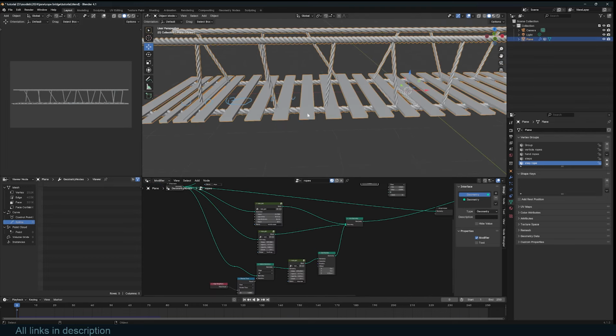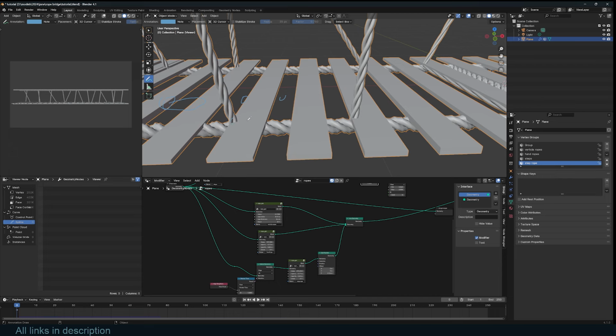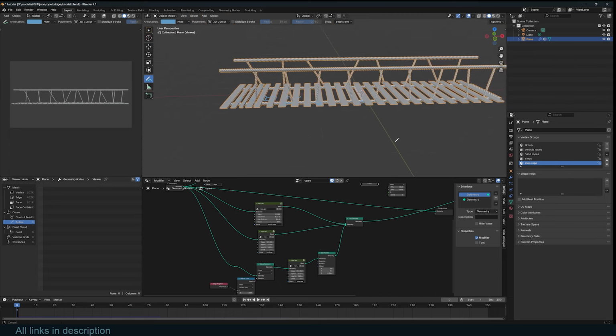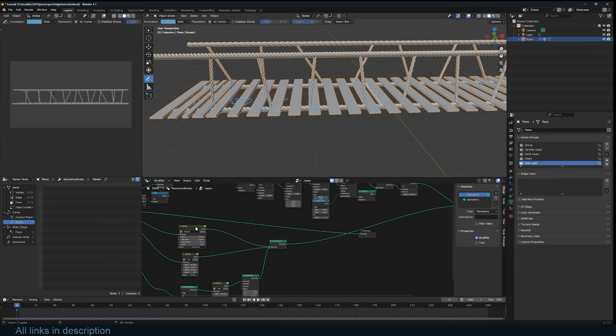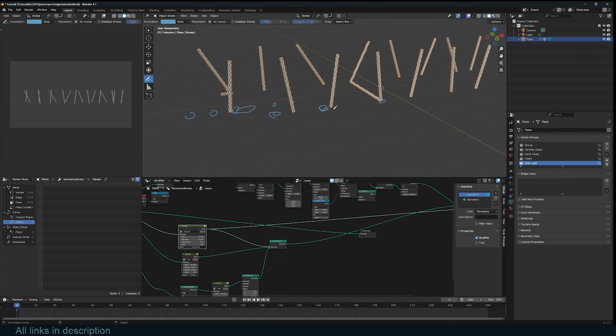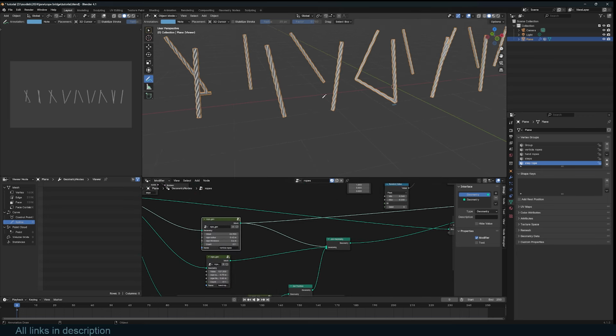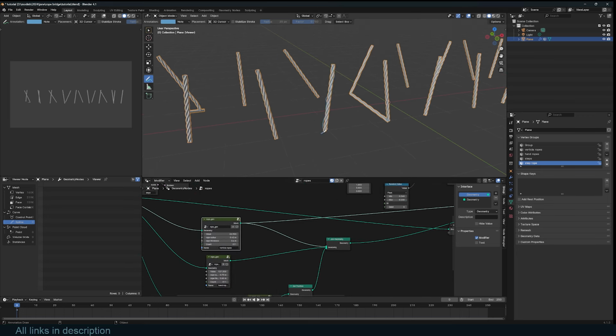Now you can add knots here to make these look tied onto this. To do that, we just need our vertical ropes, which should be this. Because we have this rope chain, we have already turned this into geometry, into mesh, but we need the original curves.